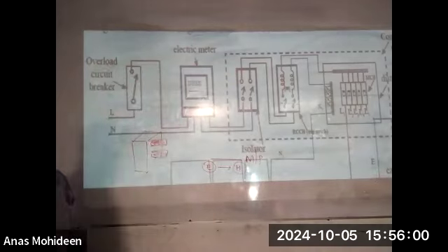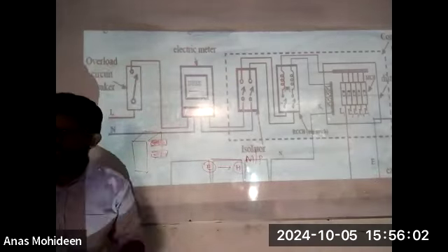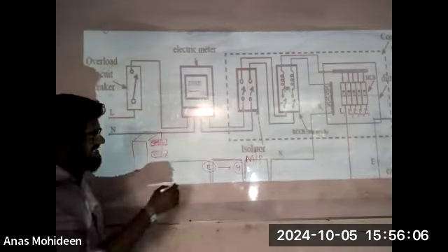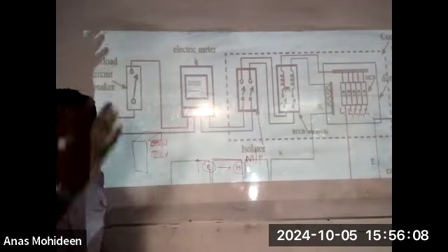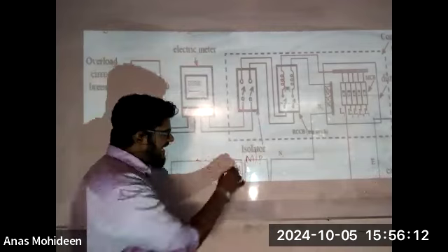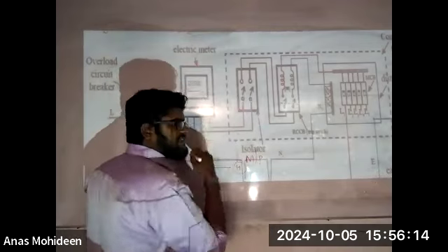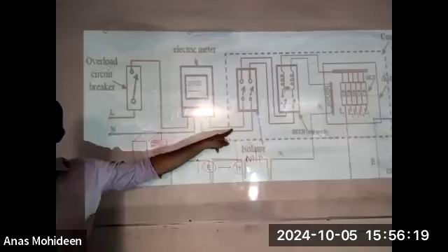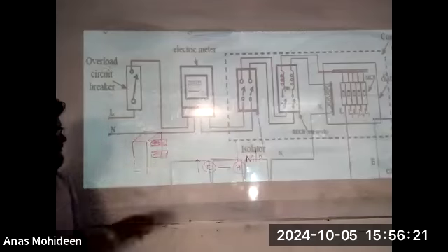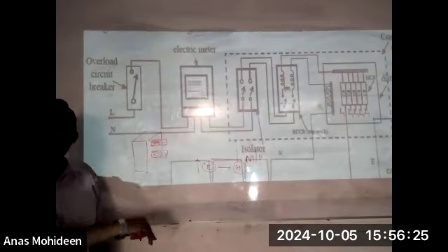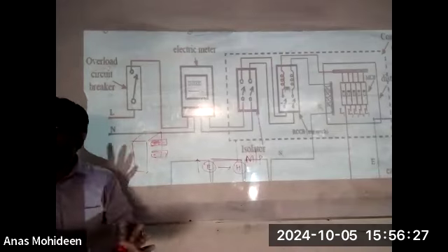Electric energy when you are supplying, along with this, it is converted to heat energy as well. We are using electric energy, there is a heat loss also. Now let's say if this electric energy is increasing more than the maximum, then heat conversion is also high. This heat conversion may pass this level. When this heat conversion passes the level, what happens? It crosses the melting point, so this melts. This is how the service fuses in older houses disconnect the supply.